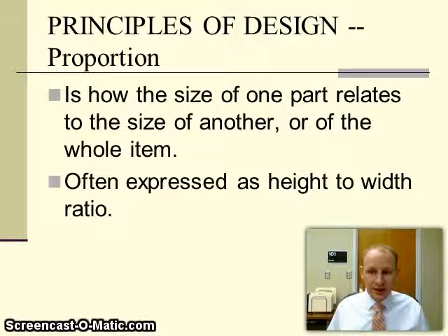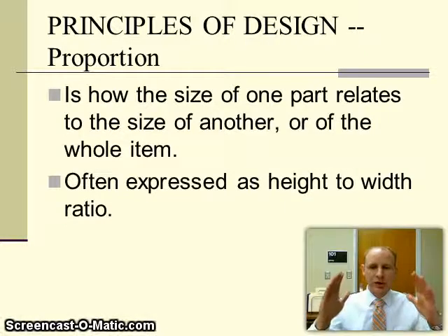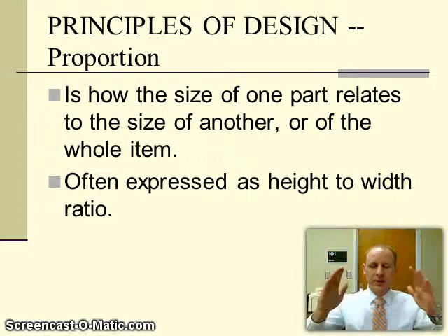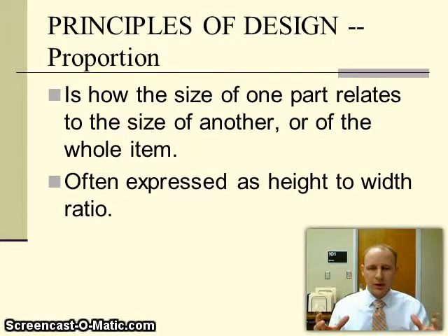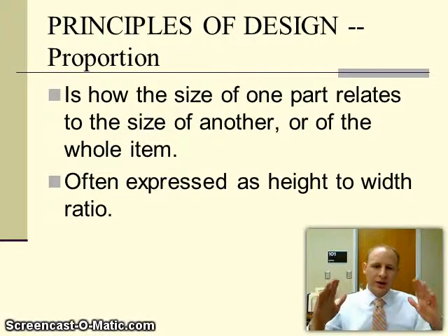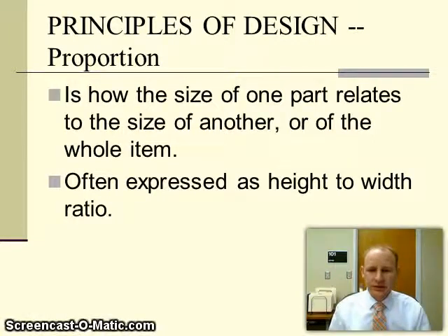That doesn't mean they have to be the same size by any means. But think about a garage or a house. When you look at the roof, if you have a really steep pitch on a roof, that roof is going to be really tall. So let's say it's a single story ranch style home. A really tall pitched roof is going to look funny on that particular house. It's not going to be in proportion. When you look at it, all you're going to see is this huge roof and not really be able to see the house at all, which isn't the purpose of the design of the house. So you want to consider proportion.